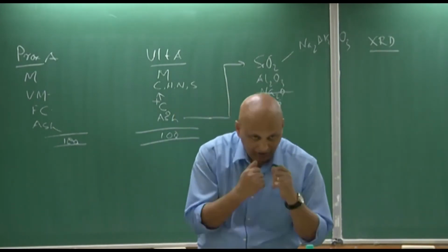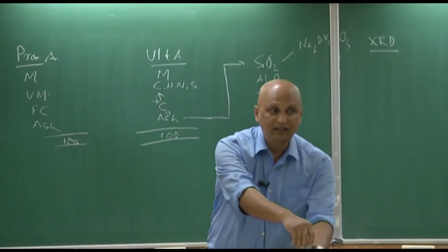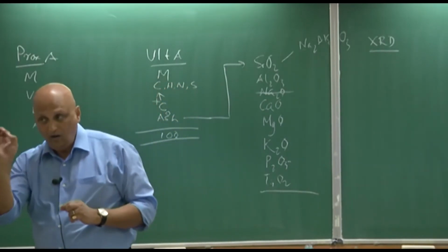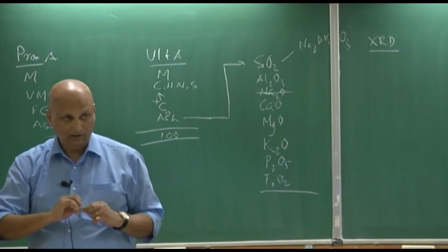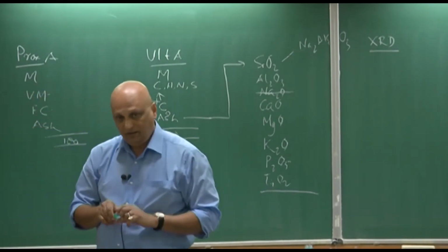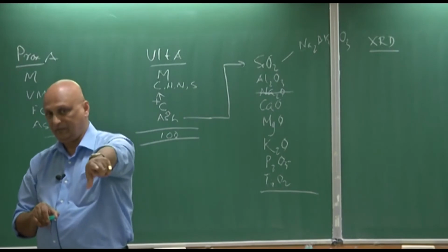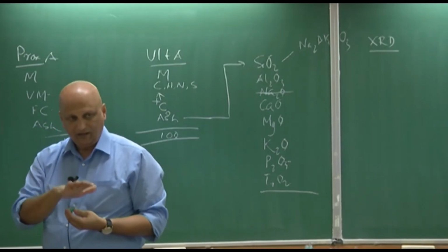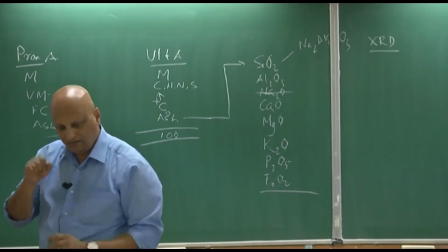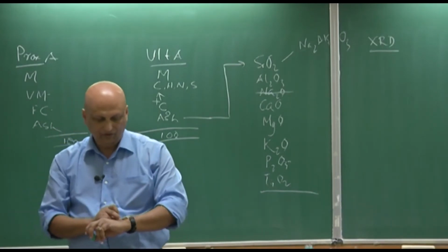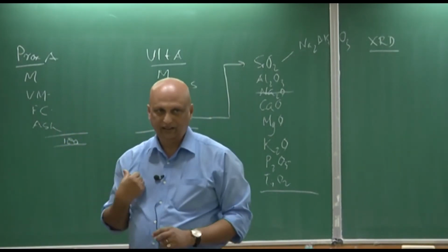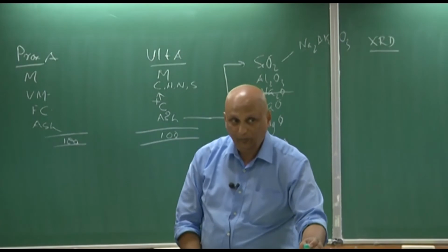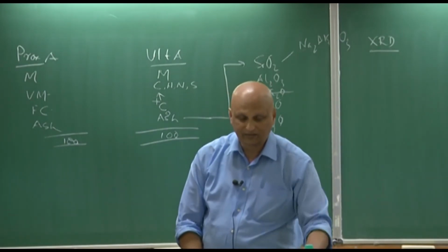So you take specially designed crucibles, these are pretty well designed, with lids on them, and the standards actually tell you how much coal you are allowed to put inside. Then you heat up the furnace to 900 degrees, preheated, load the coal, the designated amount, cover the lid, and close the furnace. Keep it for 7 minutes, switch it off, bring it out, take the weight difference, and it will give you the volatile matter, the standard volatile matter. But the point I'm making is that it is 900 degrees, 7 minutes.